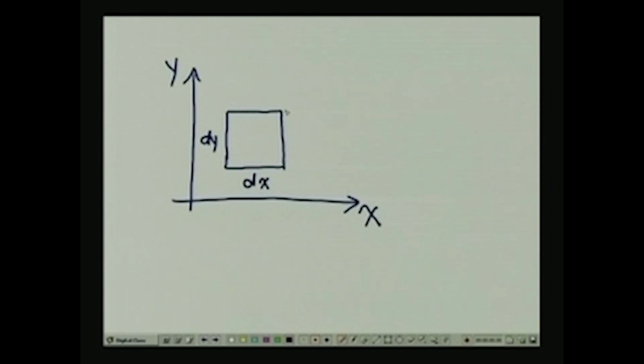So, first of all, let us consider that by some means we stretch the element in the x direction, and this amount of stretching is given by du. It is a small infinitesimal quantity, and this definition is only going to work when the deformation is small. So, that will give us the normal strain in the x direction as du/dx, as was given in the slide before.